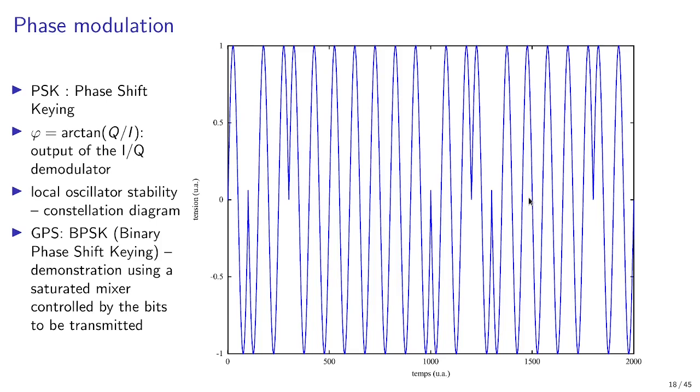The challenge of decoding the GPS signal is that it encodes the information over the phase, which requires fine phase recovery. Indeed, if the phase encodes as 0 and pi the bit state that is being transmitted, then any phase rotation due to frequency offset between transmitter and receiver will add some continuously evolving phase component 2 pi delta f t when frequency delta f is introduced between transmitter and receiver.